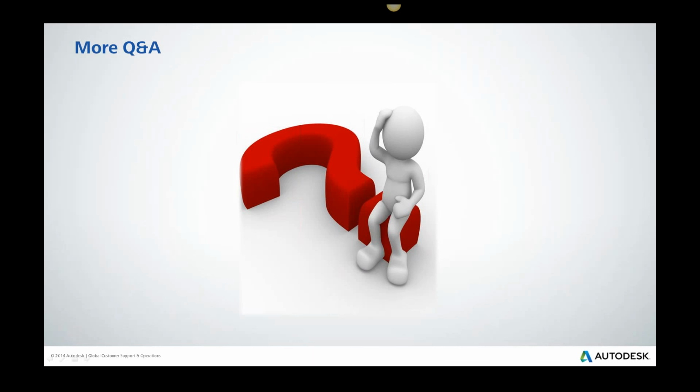So you can use it on a 2D object that isn't closed, but you get different results. You get a surface instead of a solid. Thanks, Dave. I'm sorry, Victoria, go ahead. That's okay. I didn't want to get into it since we're focusing primarily on 3D solid objects. But yes, if you extrude something that's not closed, it does extrude it as a surface.